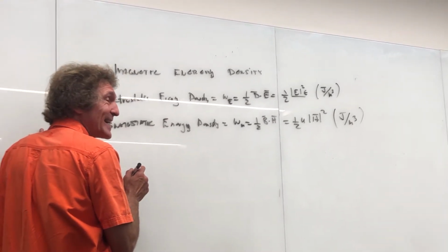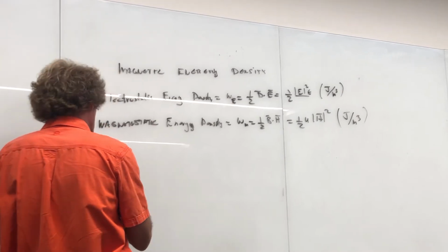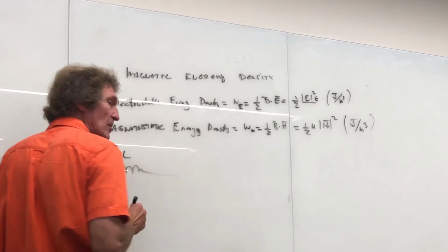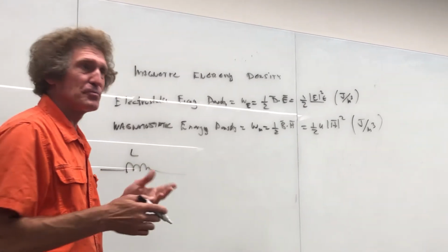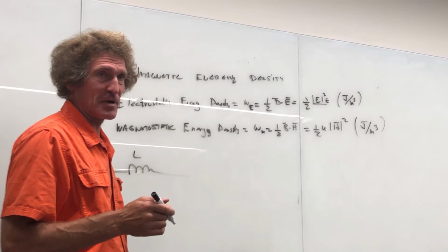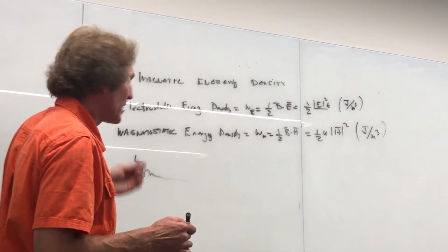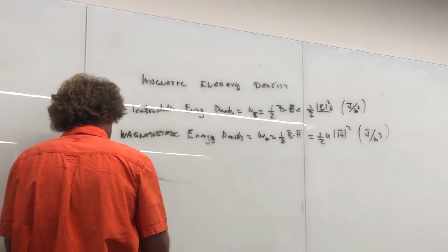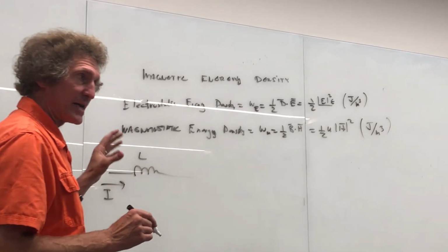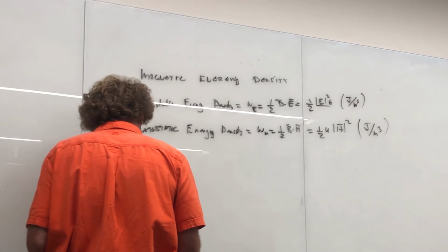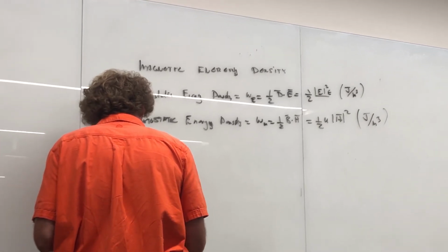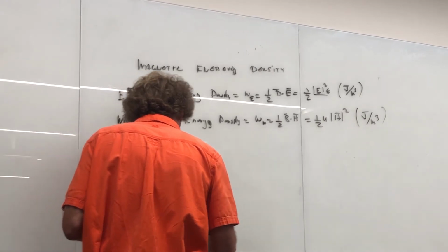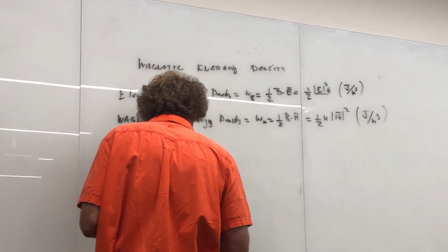All right. In general, the symbol for an inductor is just a coil of wire like that. And usually you see an L there, or if you took circuits, you see something like j100 ohms. But L itself is in henries. Well, if I put a current I in there, the total magnetic energy, I don't know if you remember this from Dr. Owen's class or whoever you had for circuits, is equal to 1/2 L I squared.